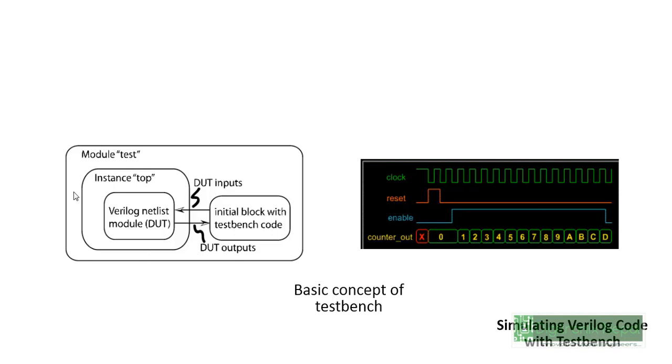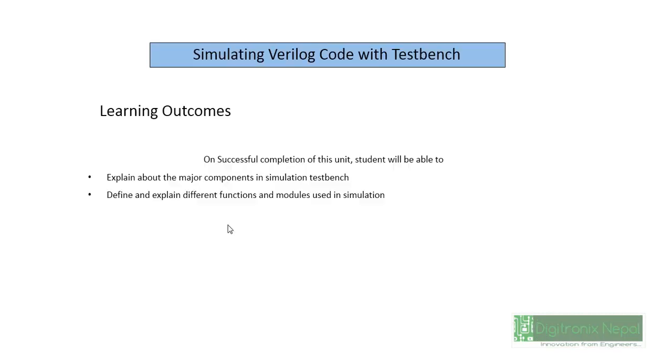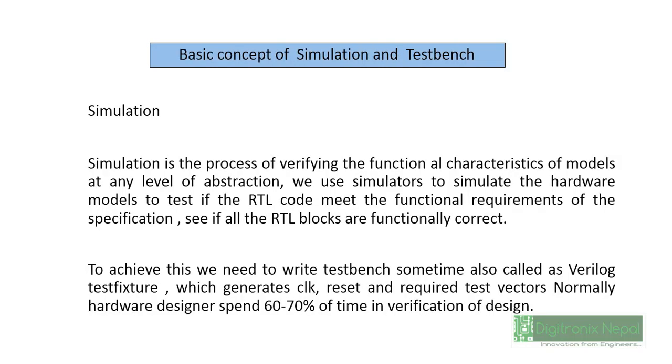So here we can see the basic concept of Testbench. Actually, we will have the top layer of the module including functionality, and inside of that module we will have the instance top, and inside of that we will have the DUT. That DUT is utilized for creating the Testbench, which includes instantiation of stimulus. After completing this lecture, you will be able to know about simulation, creating Testbench, and different functional modules of simulation.